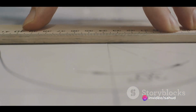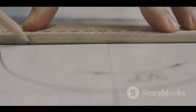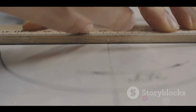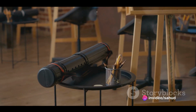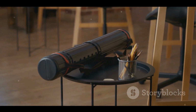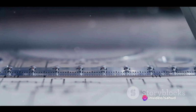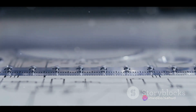Next, we move on to sketching tools. These are your brushes and chisels, your pencils and erasers. They're located on the Sketch Command Manager. There are many to choose from, but today we'll focus on the line and circle tools. To draw a line, click on the line tool, then click on your sketch plane to set the starting point. Click again to set the end point. Easy, right? Now for the circle, select the circle tool, click on your sketch plane for the center point, and drag outwards to define the radius. Voila! You've just drawn your first shapes.